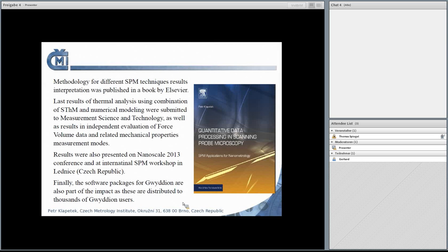Or, for example, we can use materials that are cheaper and easier to process. The example I have in mind is silicon. If we manage to produce silicon with a very high ZT, this will be great for the semiconductor industry. They don't have to move to something like bismuth telluride or other difficult-to-control semiconductor compounds. So that's one of the main drivers: increase the ZT, open new markets, or maybe improve the manufacturability of existing thermoelectric systems.